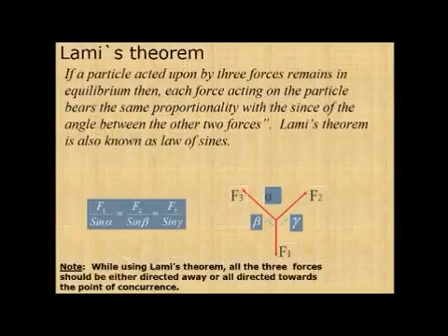Now coming to the main topic, the Lami's theorem. What does Lami's theorem state? If a particle acted upon by three forces, and I need to tell you that this is only about three forces, remains in equilibrium, then each force acting on the particle is proportional to the sine of the angle between the other two forces. That is, Lami's theorem is also known as the law of sines. This is the most important thing you need to see.